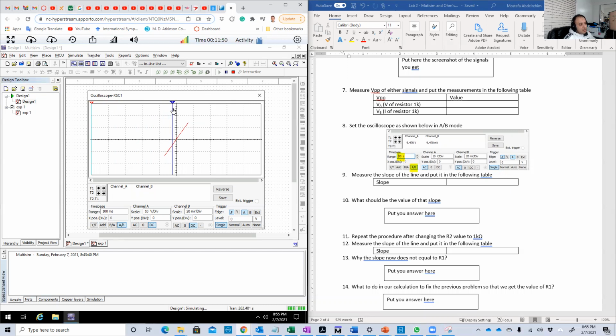We're going to notice something bad here, which is that whenever we hover, whenever we move, the reading just goes away. Yeah, maybe the reason for that is that setting here that I didn't mention. So basically, the oscilloscope has a kind of frequency in showing the signal on the screen. So we're just going to decrease that frequency. That's what we're going to do now. It's currently 100 milliseconds, make it 50 milliseconds.